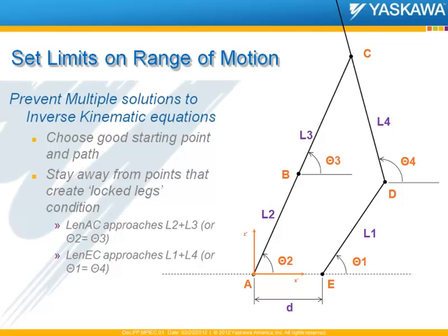But number two, you just get the mechanism into some space where it doesn't operate very well at all. So be sure that your actual path does not approach that. So we do create an error inside this block. If we get within a range of this position, it will throw an error to you. So this is one of the error conditions.